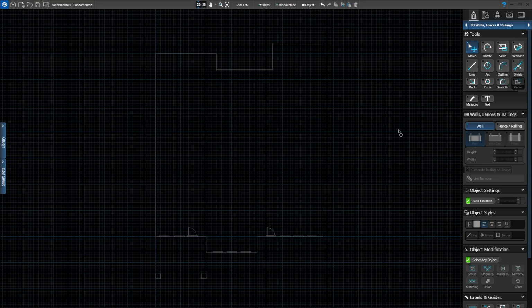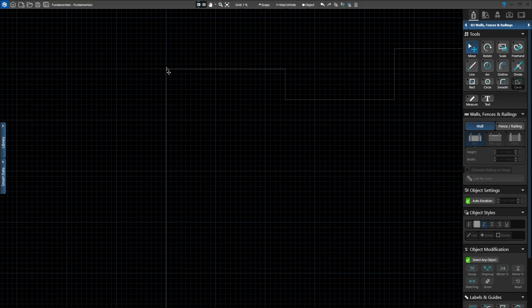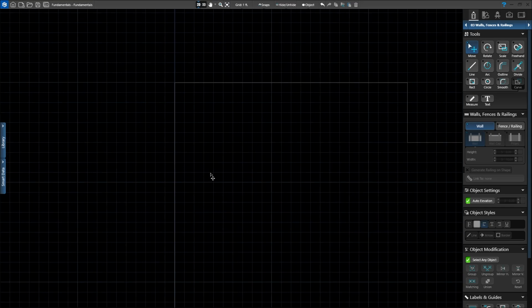We have wall activated in the walls, fences, and railing setting, but we're going to measure on the house where the wall starts on the top left-hand corner. So I'm going to zoom into that top left-hand corner. Put your cursor on the corner of the house and roll your scroll wheel away from you to zoom in a little bit closer. That's going to be our site reference. We're going to measure 16 feet from that corner down, and then we'll begin drawing at the bottom of that 16-foot measurement. Go to your panel menu and go to your toolbar.